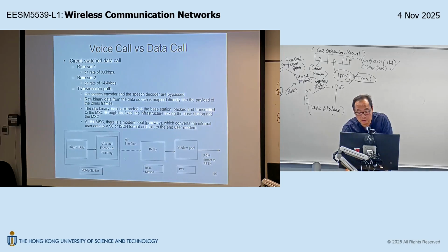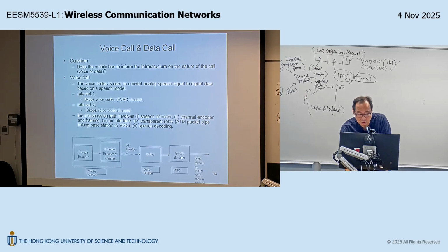But these 300 passengers are coming from a compressed speech. Okay, so this is like you pass an MP3 file to a dot wave decoder. The dot wave decoder will not be able to decode your original voice, right? Because the format is not compatible. So therefore, in order to complete the speech path, somewhere in the mobile switching center before moving to the PSTN, you need to terminate this call with a speech decoder. That is, if you think of this as an MP3, you need to have an MP3 decoder so that the output of the speech decoder becomes dot wave.